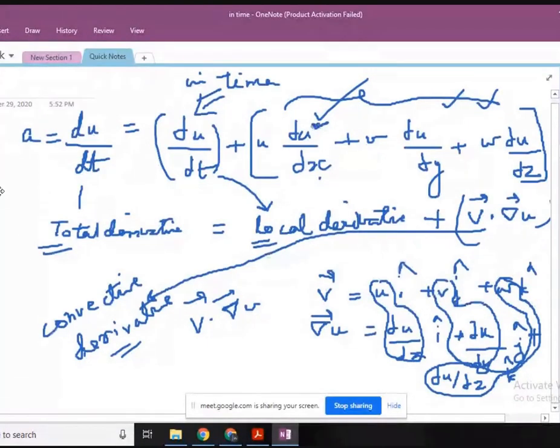Then you compare the change of that value with the other value spatially. This gives you the spatial component of variation. This is why it is called the convective derivative. The change happened by tracking the flow in space, as you moved along with the flow. This part of the change happened because the flow convected, or traveled, through space.